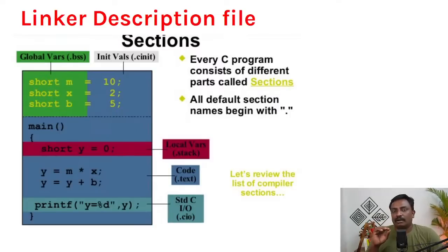But when you do math operations, you cannot write the flash memory from the C code. That is not possible. The controller cannot write the flash memory from the C code. It needs a programmer to store or edit the flash memory. So it will store it in the RAM memory available on the microcontroller. The RAM is volatile, which the core can edit easily. So a certain part of the code has to be stored in the flash memory, and a certain part of the code has to be stored in the RAM memory.